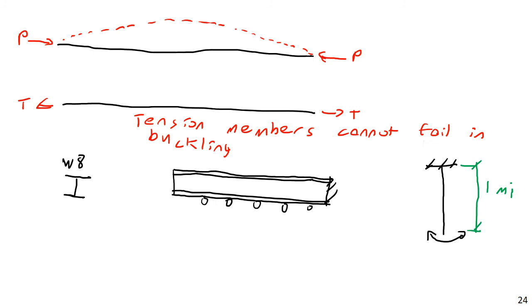I know this is a long-winded way of getting there, but we want to limit this because this is a tension member. We are designing tension members still, so we don't have to worry about a bending moment. However, anytime your members start to get too long, they start behaving like spaghetti. So what happens if you have a very long, thin member and you try to lift that thing up?